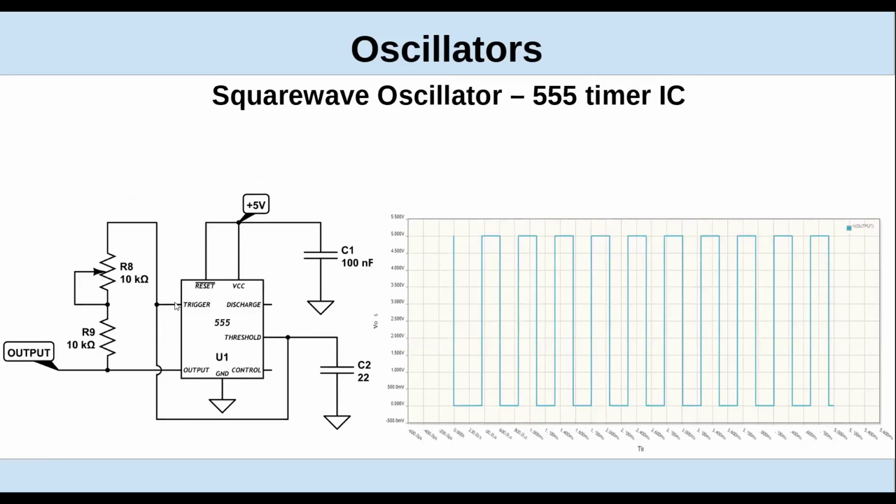The other thing we can do is buy a thing called a monostable or astable multivibrator. The typical one you see is a 555 or some variant of it. And it works by charging up this capacitor that you add through this resistor network that you add, which gives you a RC time constant.